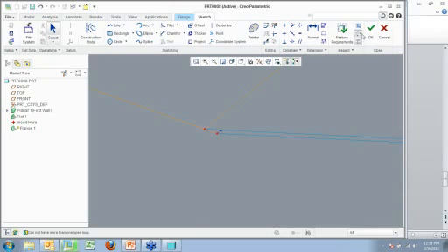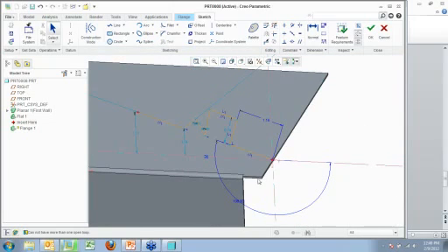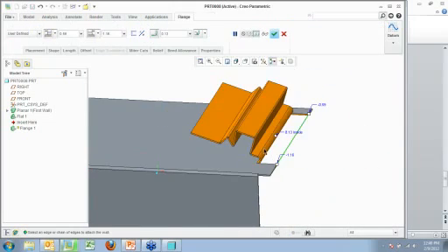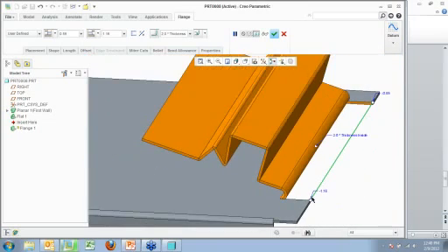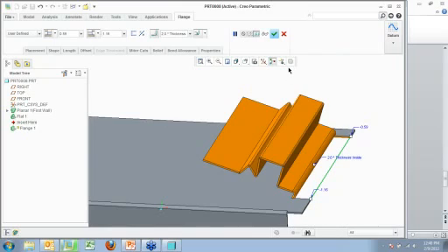See, right there, what I was talking about earlier, this highlight open ends. That's a perfect example of a time when that saved me. So come in here and I'll just trim that off. So let's say here, yeah, both the ends should be open. So now see that crazy wall I just generated? I can go in here and specify I want it to be 2 times thickness for all these bends, and so I have to actually go in there and change those individually, it looks like. But this is something that a novice with sheet metal was able to create in 30 seconds of playing around.